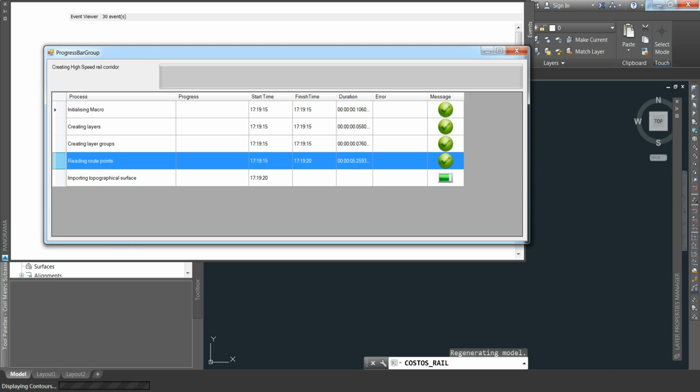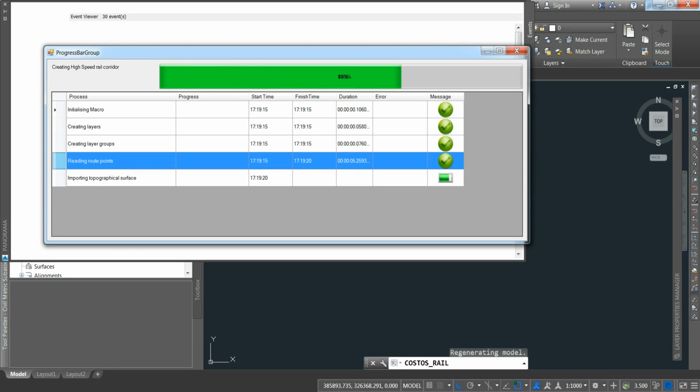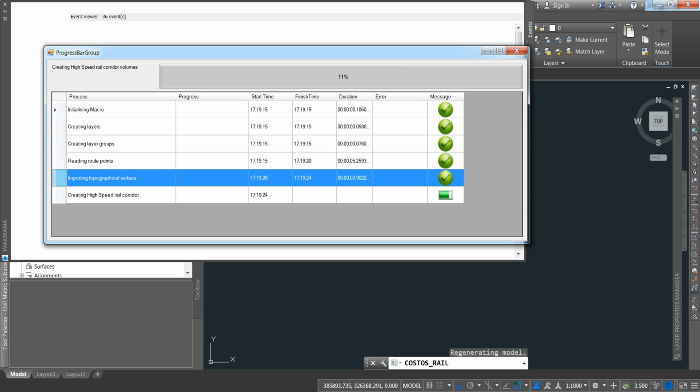So to obtain geographical and infrastructure information, these are using the government's free big data sources. What it's going to do is overlay the route onto the existing topography from the government, and then from there you can overlay the existing infrastructure networks such as roads, A roads, B roads, minor roads, different sizes of river, and railways. When the program finds a particular asset crossing our route, it will split the route and put bridges there, and then await the user to define what's happening more specifically.